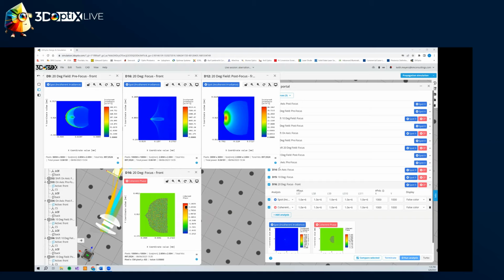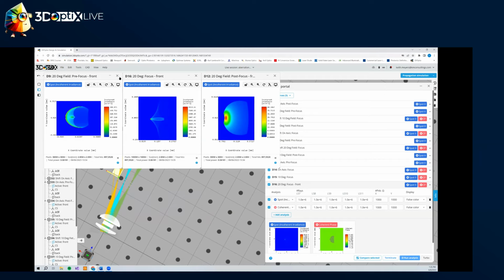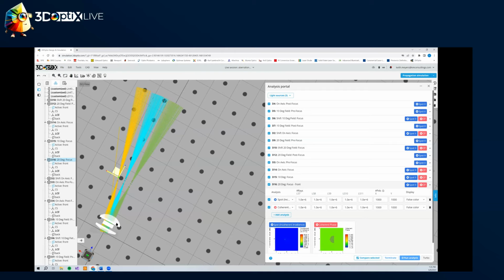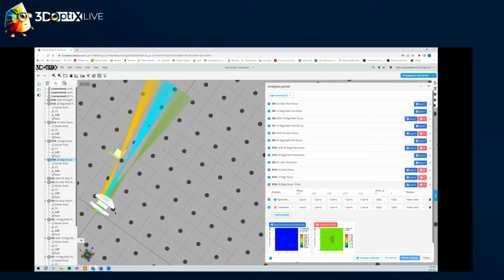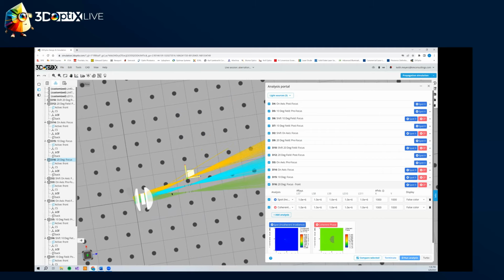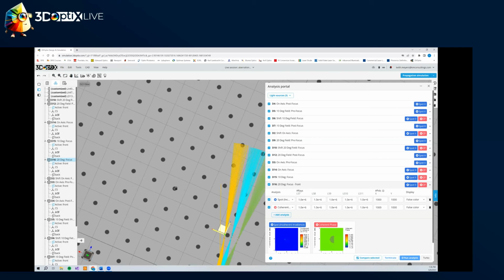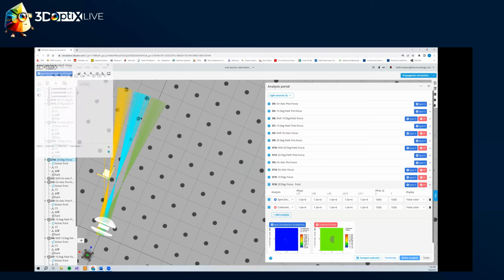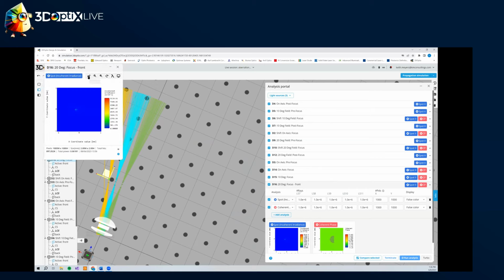All right, so now we're going to change the orientation of our lens system. So we're actually going to move the last lens in our system here. We'll pull this down. We're going to move this last lens a little farther out, and we're going to see what happens to the optical system. If it's better, worse, or no change. Before we do that, we are going to look at the focus, and we're going to lock the focus of each of the fields so we can compare them.